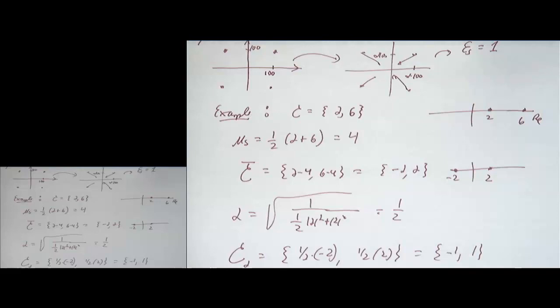So okay, the zero mean assumption, I should have mentioned that, is also there because DC doesn't propagate. If we had a non-zero mean signal, that would mean that our x of t was also non-zero mean. But you can't send a modulated signal that has essentially a DC value.